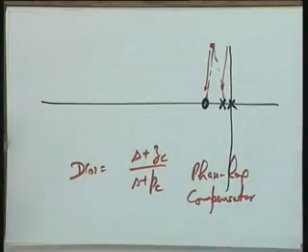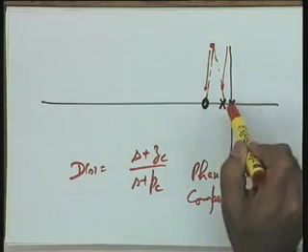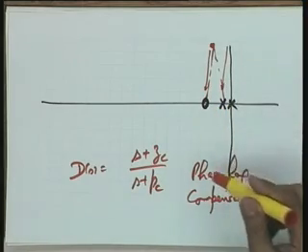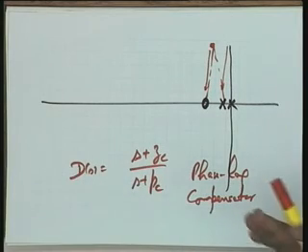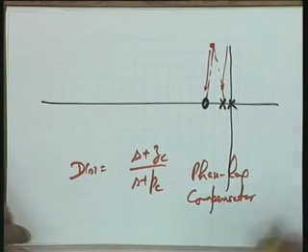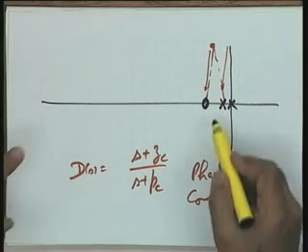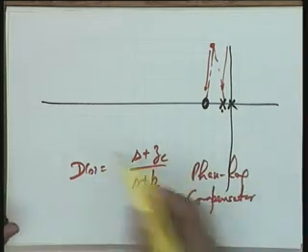As I said, I am going to give you the complete picture with respect to the two design examples. Here you can see, instead of placing the pole exactly at the origin, I place it nearby. And if I place it nearby, in that particular case, the requirement of meeting the steady state accuracy requirement as well as meeting the transient requirement may be satisfied, and I add flexibility to my design. I can select now the pole, I can select the 0, and I can select the gain also.